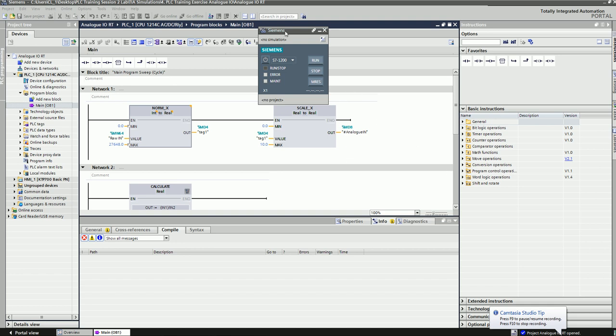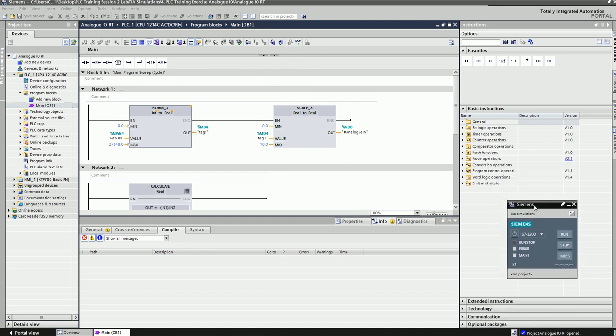Device. Now I will discuss how to configure analog inputs and outputs in the PLC S7-1200 with TIA Portal. So here you can see that I have the two main blocks, two main instructions for the analog input and output conversion, NORM_X and SCALE_X. What NORM_X does is convert the raw values to 0 to 1, that is, it normalizes the raw values. And SCALE_X performs the scaling function.